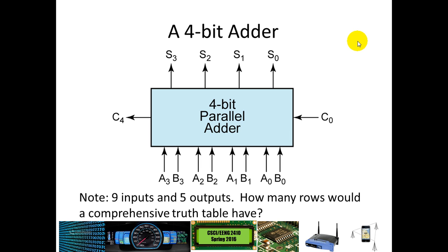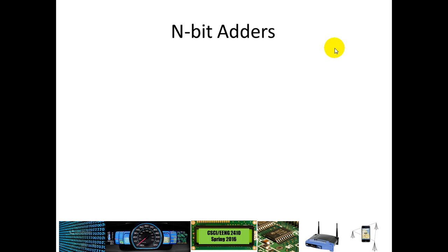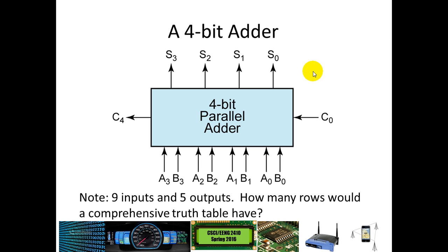We can simplify that a little bit and showcase this as a nice 4-bit adder. So in this case, not sure why my slide keeps trying to advance. So in this case, we could write a 4-bit adder with 8 such inputs down here. So we could have our least significant bits for A and all the way up through our most significant bit for A, least significant bit for another number B up through most significant bit for another number B. And then in this case, our sum would require up to 4 bits. So with a 4-bit input, we actually might also have a carry out here.